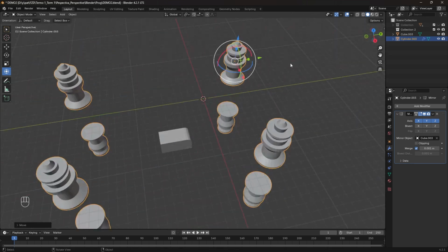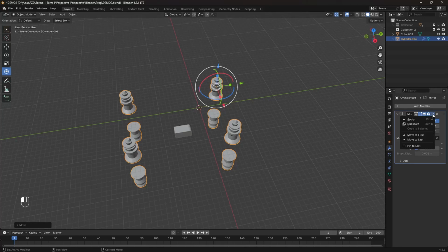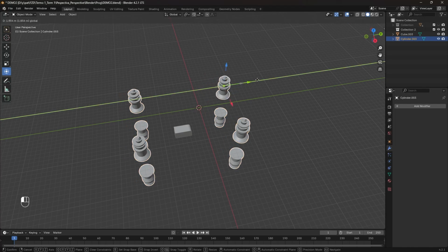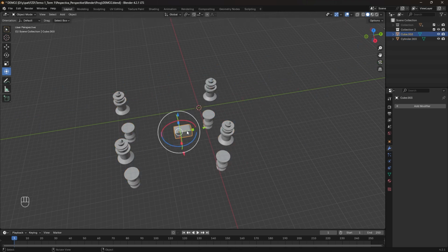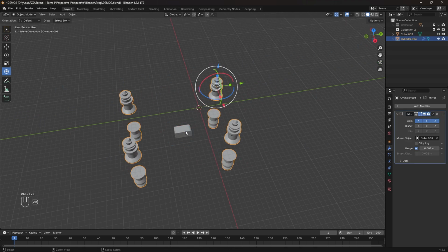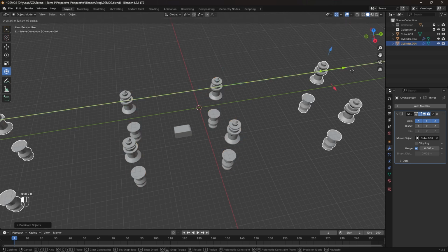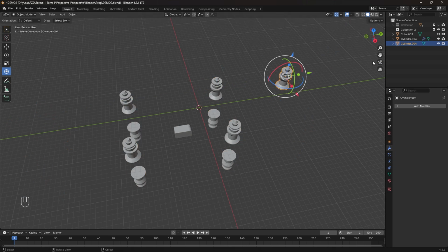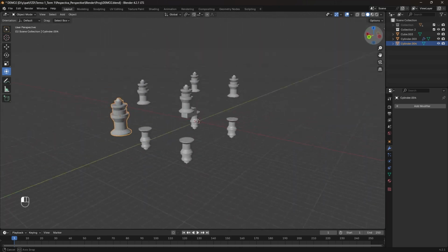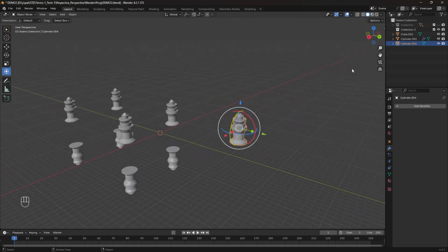So if you want to apply the mirror, you can go here and apply. When you apply, this becomes one object, and you will no longer need this reference point, but I will not apply. Let me duplicate this. To duplicate, you hit Shift D and click, and you will be able to do this. So I will remove this modifier, and I will go back to my mesh over here.